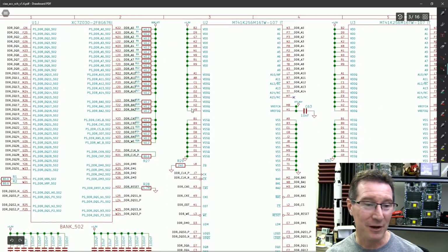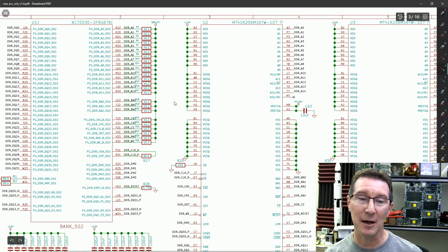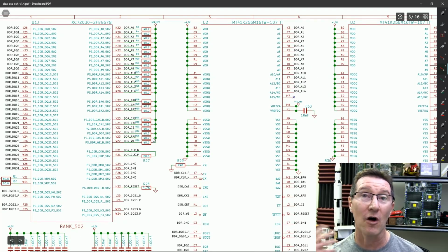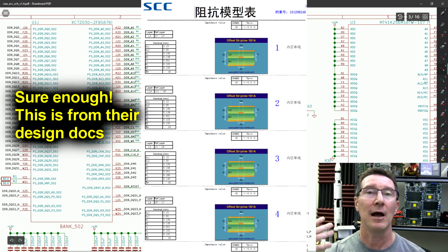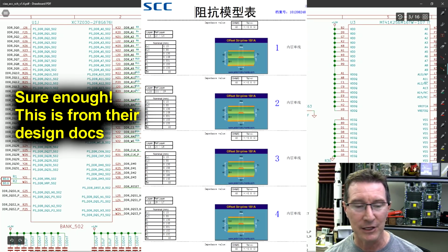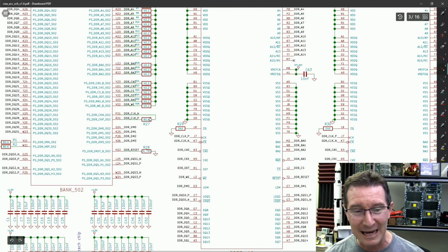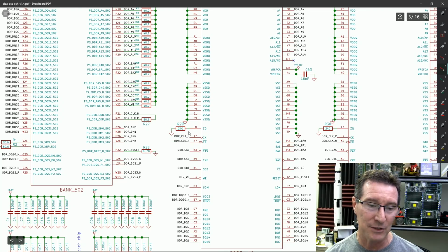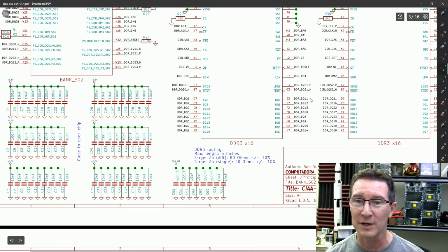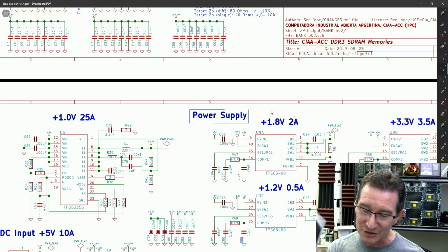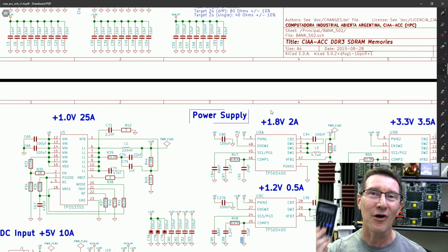Then if we just quickly look at some of the memory on here, look, we've got termination resistors, 40.2 ohms. Yeah, we've got a lot of them. That's fine. This is obviously popped out of their polar impedance calculator, or whatever it is they use to calculate the transmission line impedance. We've got 80.6 ohms here, for example. Not sure what that one's doing at 240 ohms and things like that. So all of these oddball values will pop out of your computer here, but don't necessarily blindly follow them.